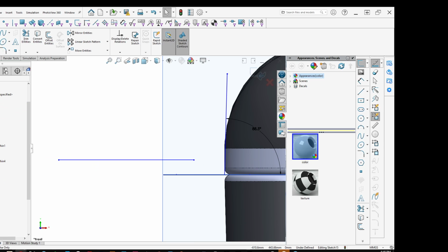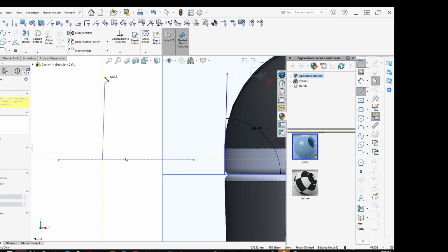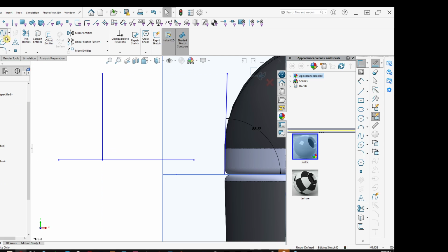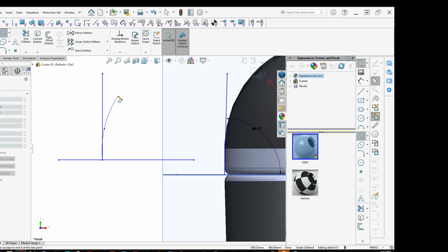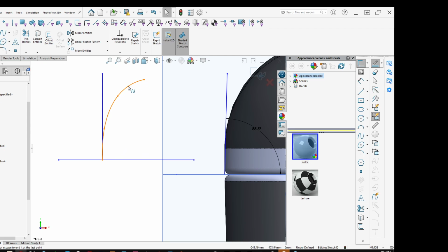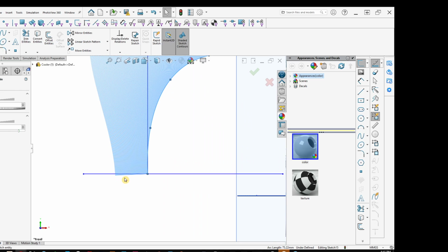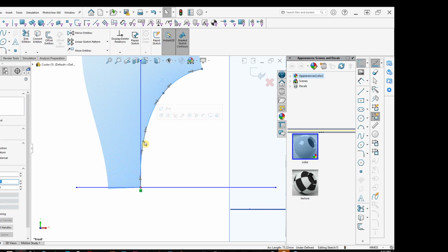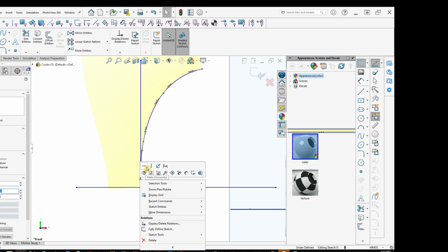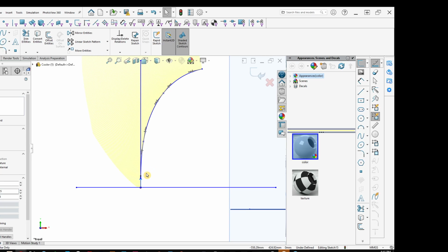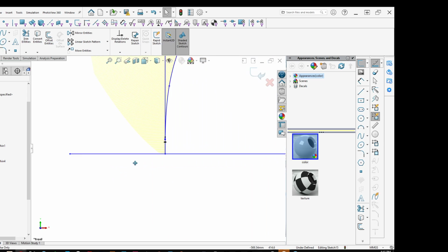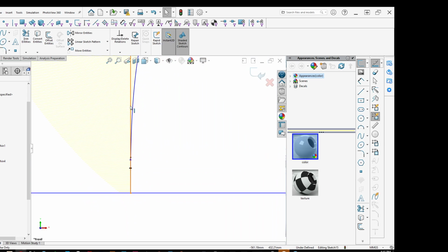Because if I'm drawing a spline from a certain point, and let's say the point is right here, and I'm going to draw my spline like this, and I want the spline to look like that, and I do that, I'm going to check my curvature, does exactly what I want. Oh, wait, it's not tangent, okay, so let's just come in here, we'll make that tangent. Okay, not what I want, but this looks good. Well, here's the problem now. I have to then come in here.